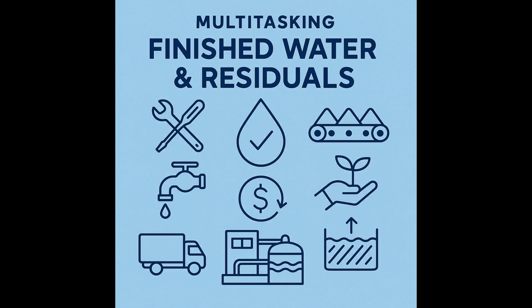What are the costs involved? The costs and logistics can indeed be significant. Key cost drivers include how dry the cake is, percent solids, because that dictates hauling weight, the hauling distance to the application fields, the permitted application rate, how many tons per acre, field accessibility, which can be seasonal or weather dependent, and of course, the costs of compliance sampling and analysis. And managing the trucks must be a big part of it.